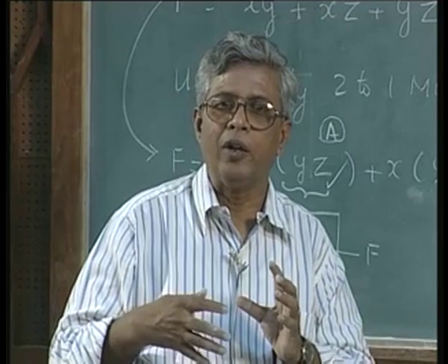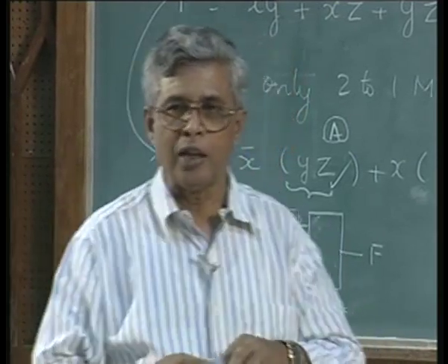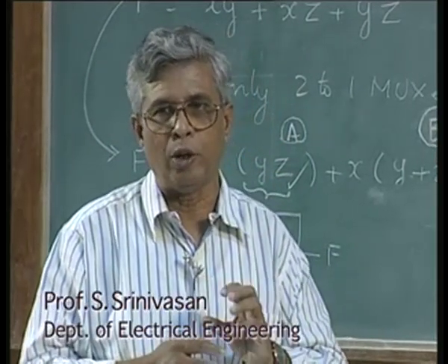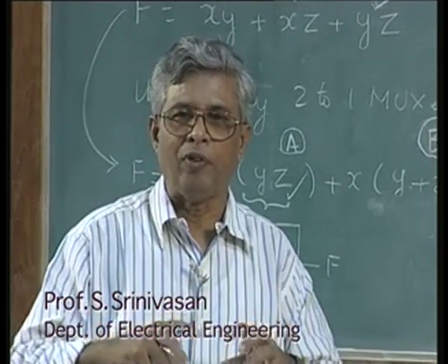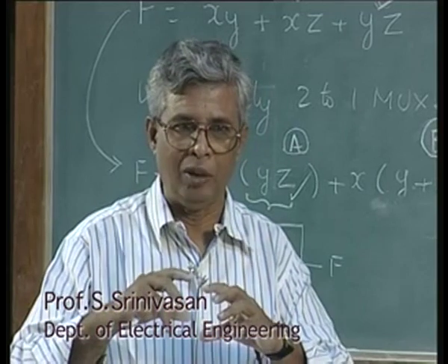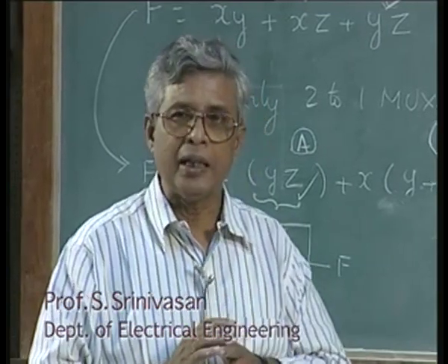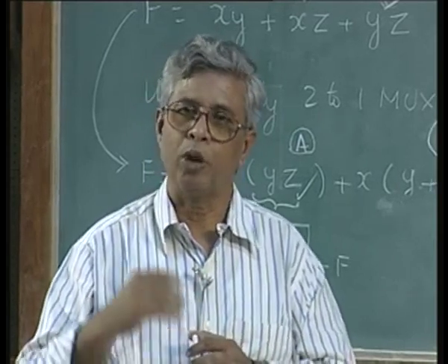A huge function will be given with several inputs and several outputs, and there may be several functional blocks with a variable number of inputs and outputs. All of them should be mapped onto a uniform hardware where a uniform type of functional block will be available, and that will be used for synthesis. We will stop with this, and tomorrow we will see how to do the same type of implementation using a programmable logic device.